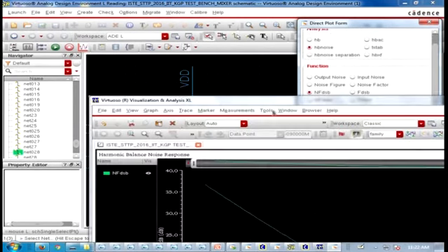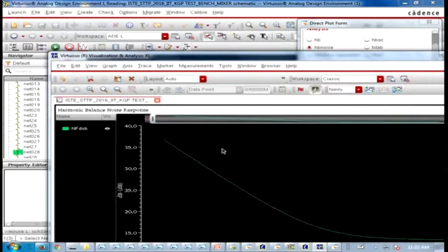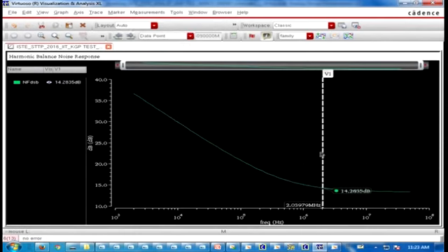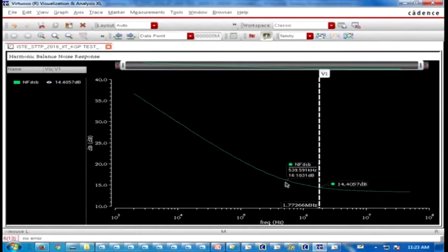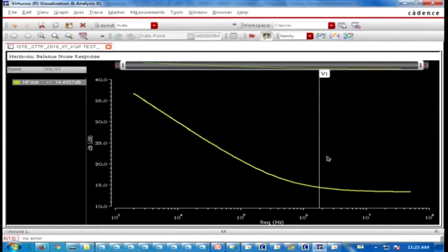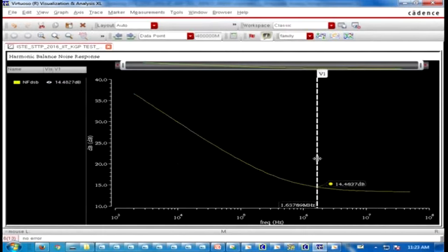So it is a DSB. That's what we have gone into, the DSB noise figure. So find it. How much is coming? Minus 14 dB. So 14 dB is your noise figure. Don't bother about that because you have an LNA gain, so that 14 dB will add a very negligible fraction to your system. Anything else you want?